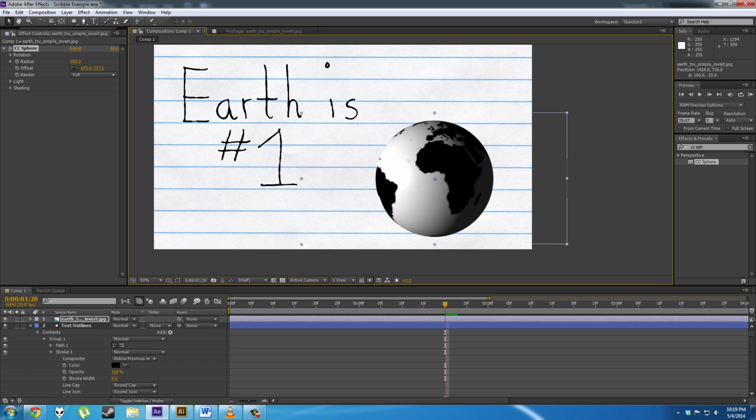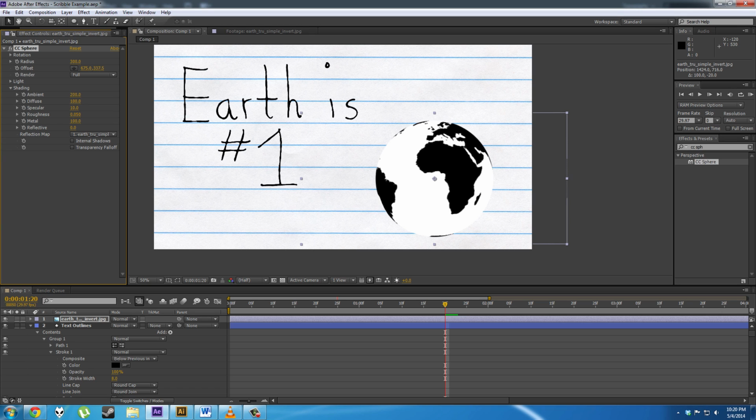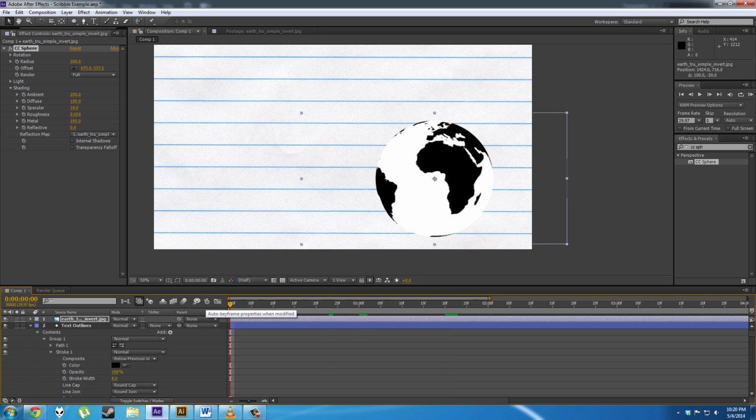Now, if I were to apply the auto trace to this right now, not only would it try to apply the auto trace to the wrong region, which is the white region, we want it to apply to the land masses, not the oceans, but it would also freak out because of this gradation, because of the shading. First things first, we'll get rid of this shading, and to do that, we'll go into the shading tab and bump up the ambient to its maximum volume, so it's completely two color and no gradations anywhere. Now this is almost ready to be traced.